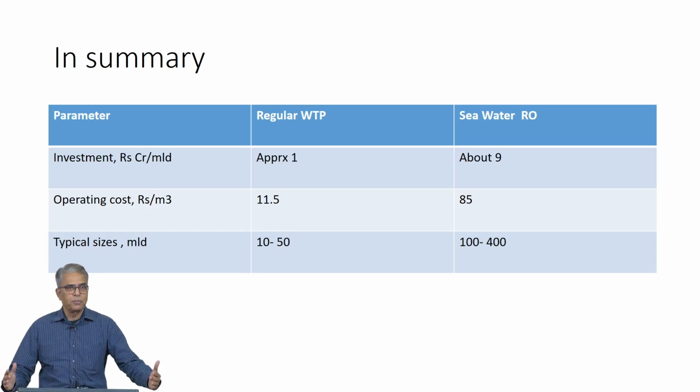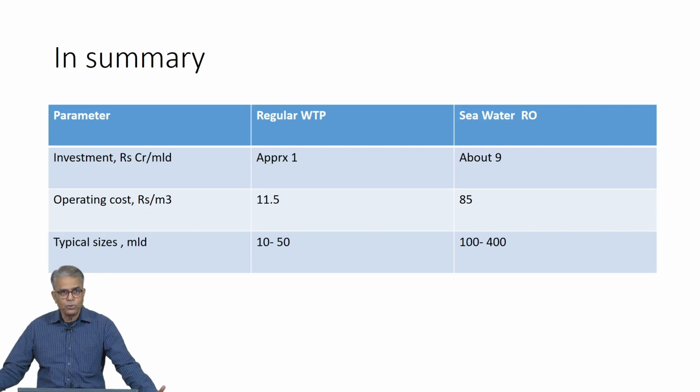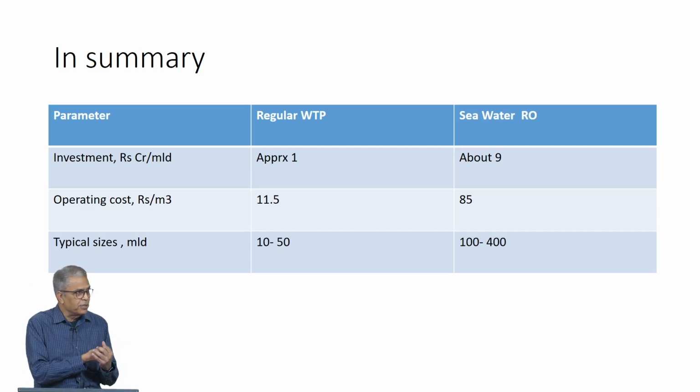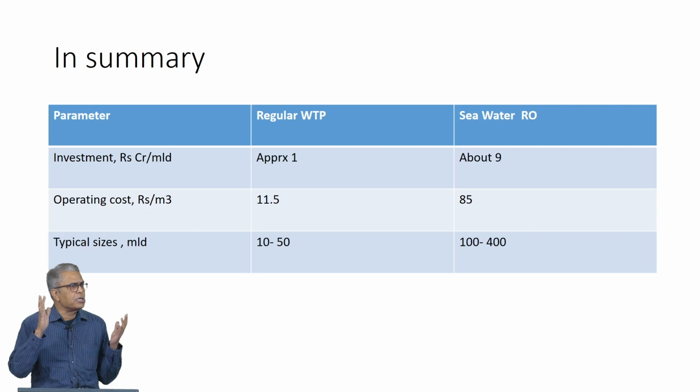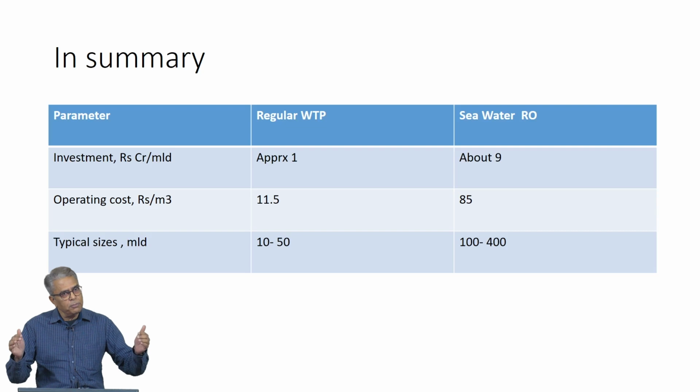In the case of the water treatment plant, it starts from the river or lake and ends with the outlet of the plant. Subsequently how it goes to an overhead tank, from there to a community fountain or to individual houses, taps, etc., that is not included, because that is so site specific. There will be additional cost involved there, because there is a pumping cost at least, plus laying the pipelines, all sorts of costs: digging, closing roads, whatever. So this is only the battery limits plant.